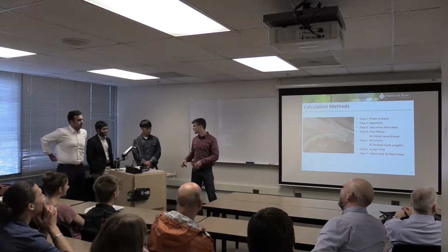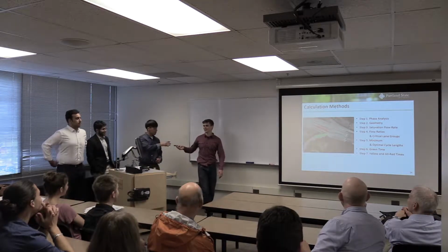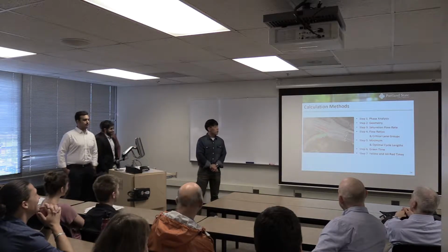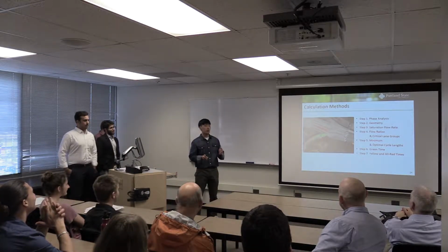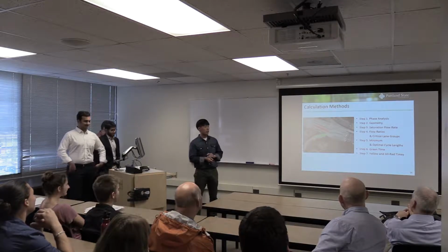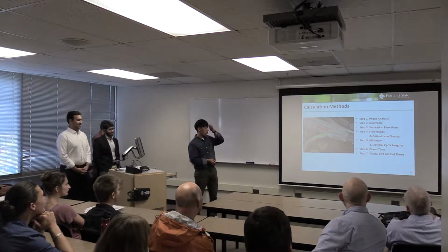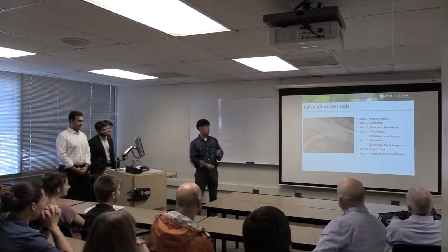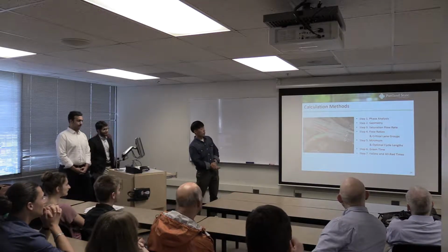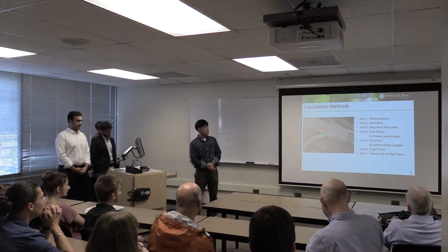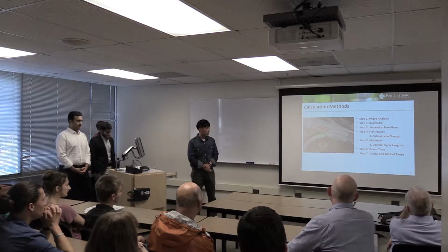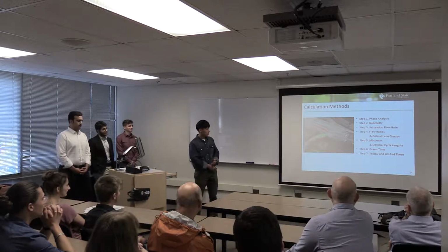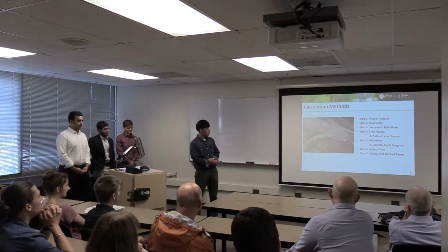And so up next, Jay will do theoretical calculation for us. For signal installation, I would like to talk about how we approach this problem to calculate our signal timing. So we referred to the Highway Safety Manual with 7 steps. Step 1, phase analysis. 2, geometry, saturation flow rate, flow ratio, critical lane groups, minimum optimal cycle length, green times, yellow and or red times.